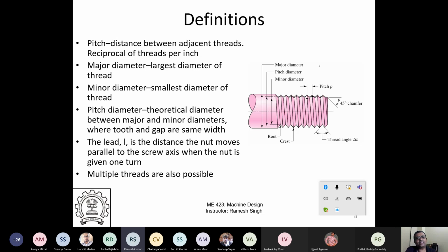All the drawings are in meters, millimeters, dimensions are in millimeters. I actually worked for a consultancy company where we worked with a lot of refinery drawings and design of refineries. So all the foundation of the pump will be in millimeters or meters, SI units. The flange of a pump would be in inches.